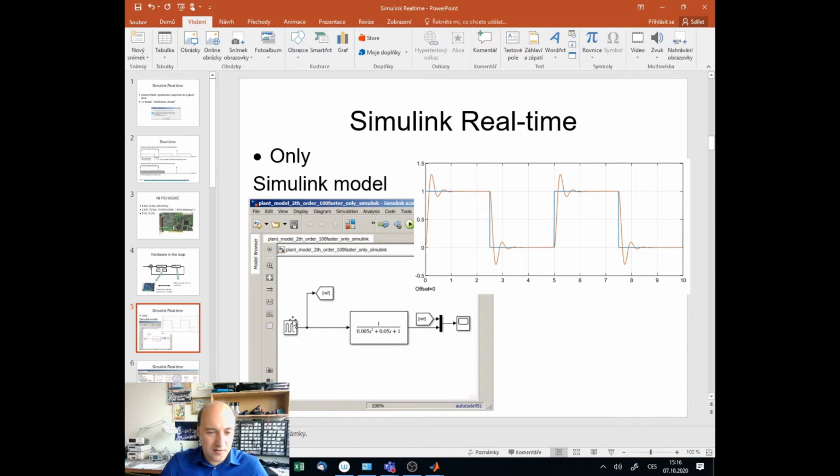So what I will do in the Simulink model is create an input signal here, which will be a rectangular signal. This signal will change from 0 to 1, will last for 2.5 seconds, and then for another 2.5 seconds it will be at 0. And the reason why I have this long time in the simulation is simple. I see that the response is here, and now it gets attenuated, and here we have a steady state.